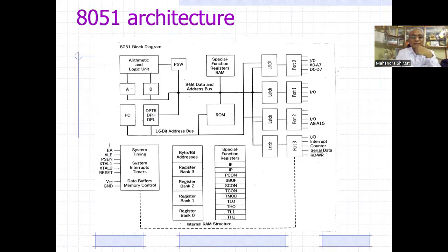And then this block is also going to control the interrupts and the data buffer memory control. इसीलिए क्योंकि whenever we will be transferring data from microcontroller to outside memory or from outside to microcontroller, we need data buffers. क्योंकि उस टाइम वो डेटा बफर्स में स्टोर करना जरूरी होता है, and that is why data buffer controls are there.